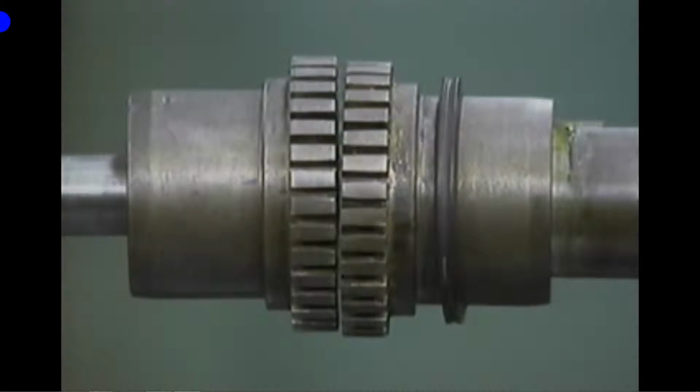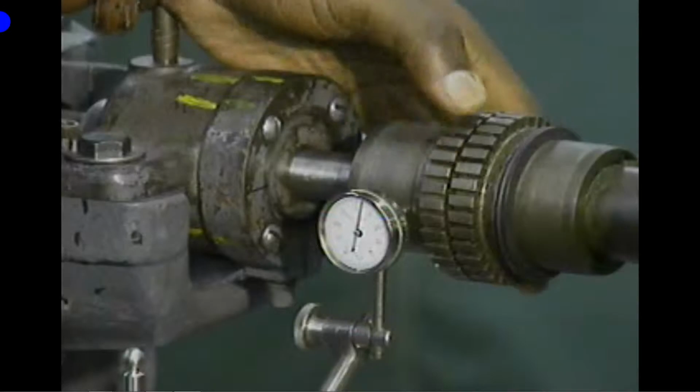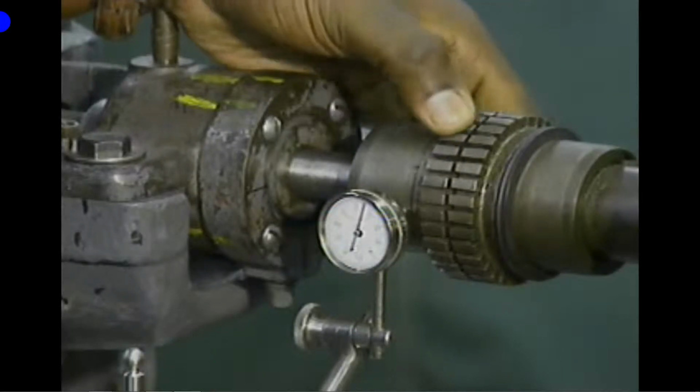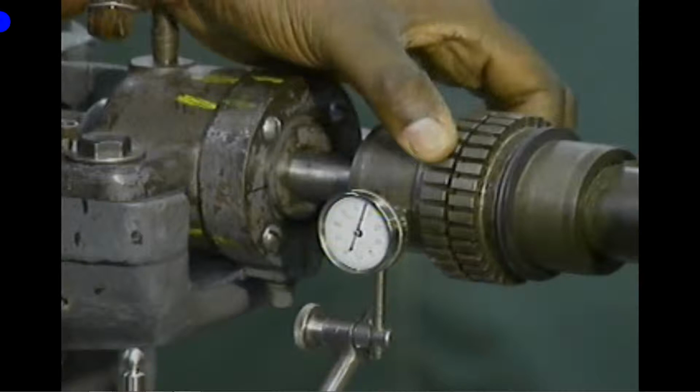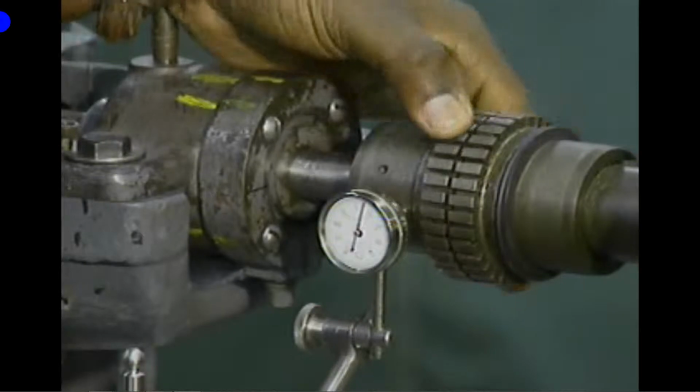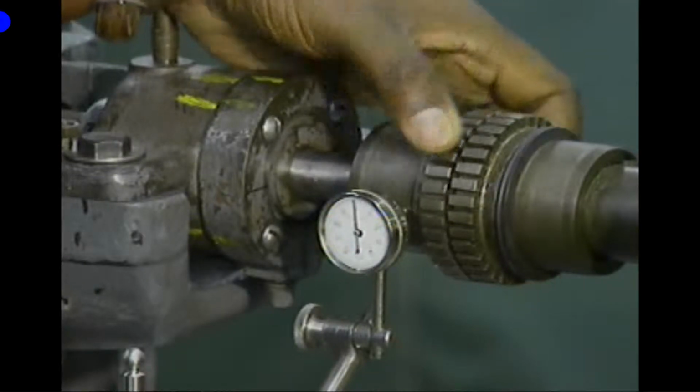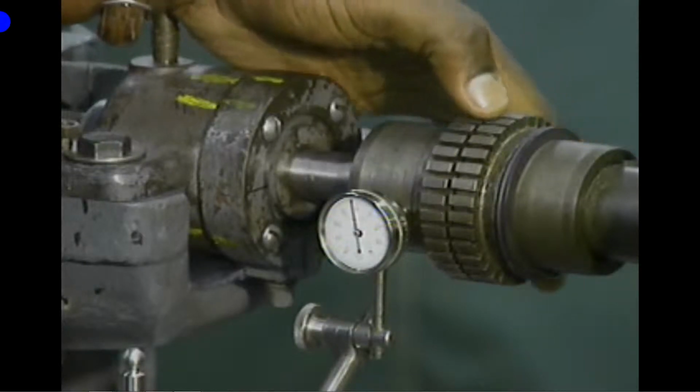Another common cause of vibration in rotating equipment is shaft misalignment. Even a small amount of misalignment between shafts can put additional stresses on the shafts and their bearings. These additional stresses produce their own distinct vibration. Vibration can also be caused by a shaft that is bent or out of round. The effect of a bent shaft is similar to that of a misaligned shaft.